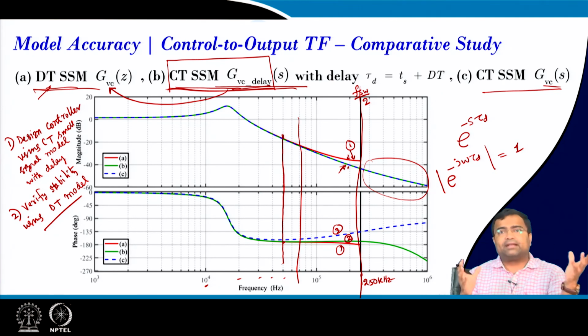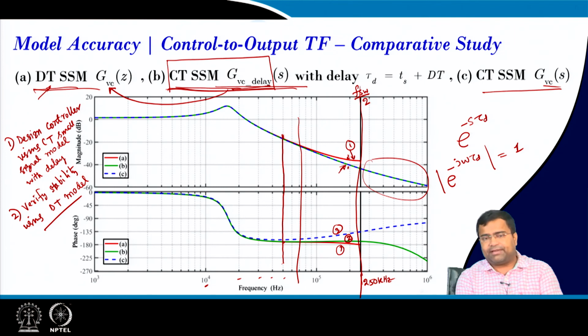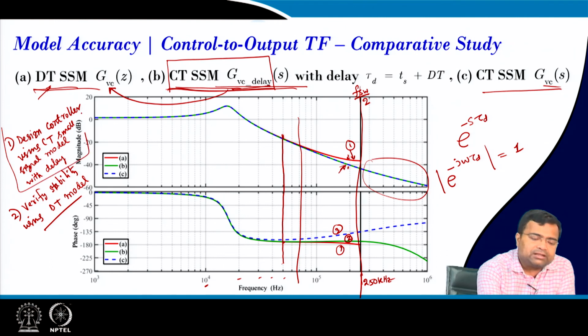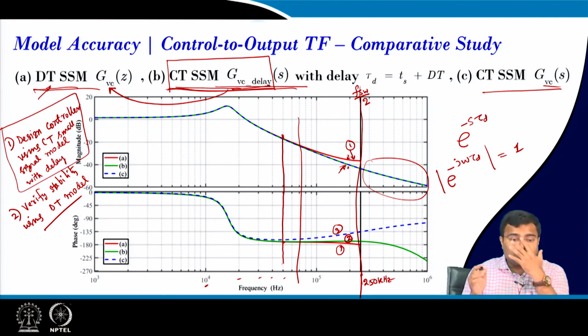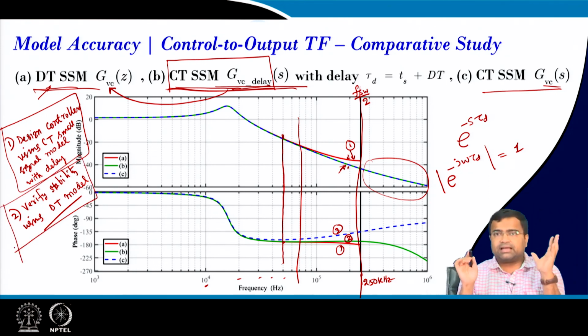so you can predict the fast scale or the subharmonic instability due to sampling, because in this course I will be showing that even for low duty ratio, or even the condition where the analog control is perfectly stable, if you introduce a sampling delay, that not only causes some deviation in the phase, that means it will slightly degrade phase, but more predominantly it may introduce subharmonic instability which cannot be captured by this model. So that is why this model is good in order to design the controller, but finally we have to check the stability by this discrete time model.